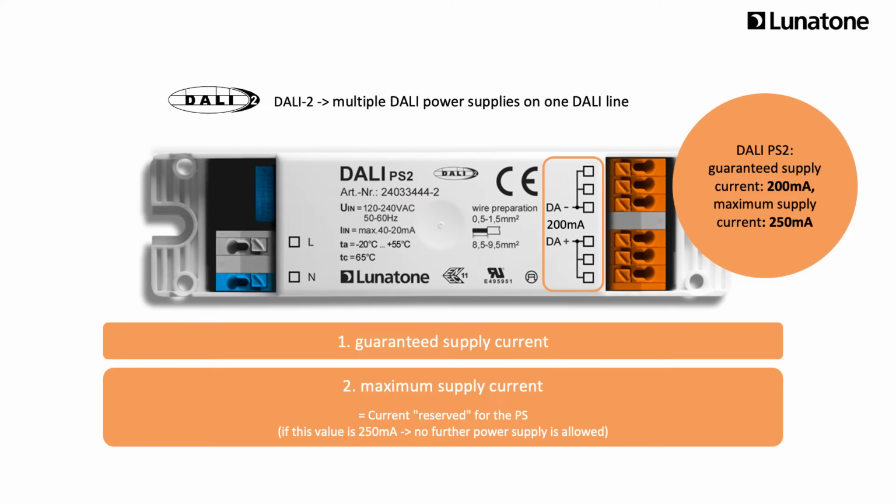The guaranteed supply current states the power the device offers, and the maximum supply current shows the maximum usage allowed. If the maximum supply current of a DALI power supply unit is 250 mA, it takes up the entire range permitted on a DALI system, and no further power supply is allowed.